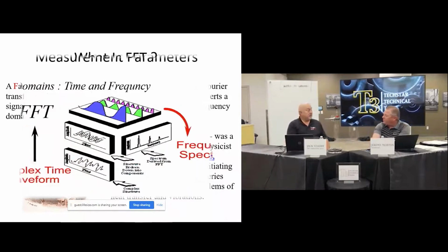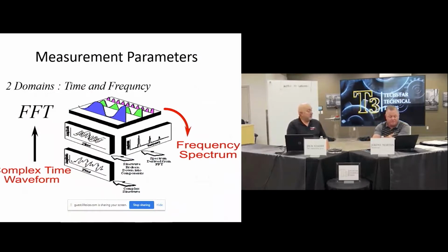And I think one of the important aspects here is this is ultimately what we're trying to gather from the vibration data. If you go with a 4 to 20 milliamp transmitter, all of this is basically null and void. You may get an overall vibration amplitude, but all of this rich data that you're getting, the FFTs, you basically lose all that. Right. So you may be able to catch a trending upward vibration signal, but that's about the best you'll be able to do. You can't tell what's causing it between all the failures that you listed earlier.